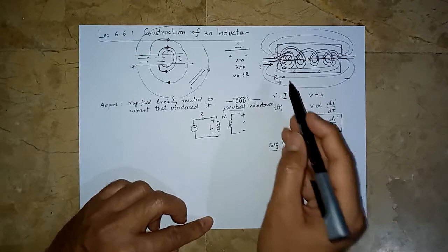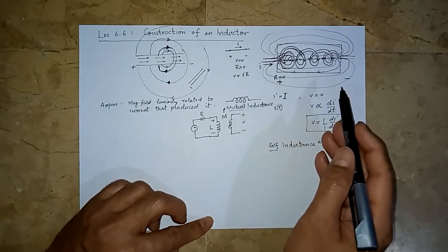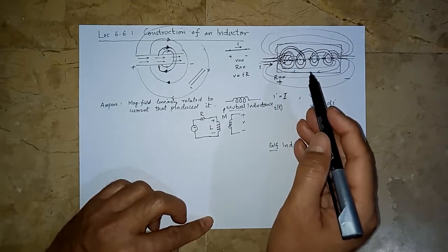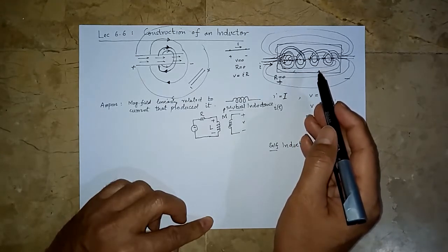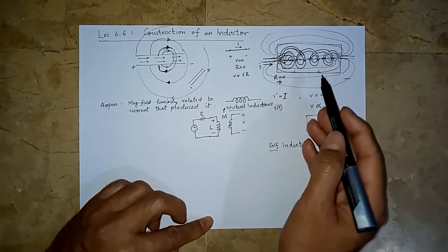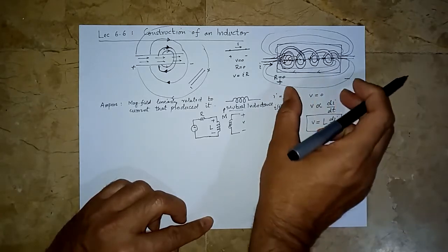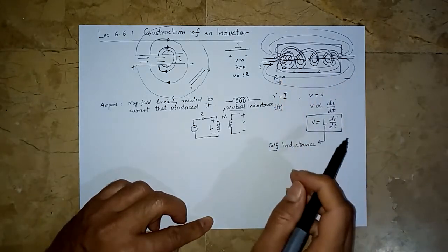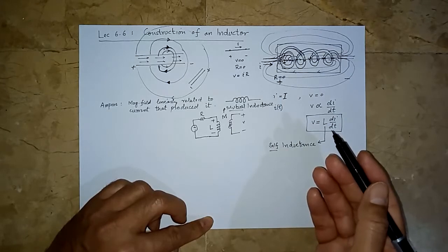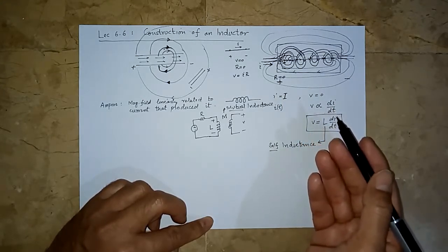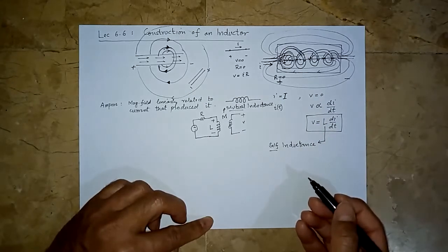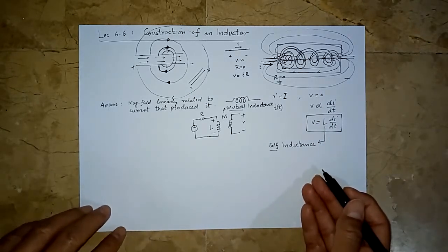This is the magic of this coil-like structure. We are going to get a magnetic field created, and that magnetic field linking with the coil itself is going to experience a voltage induced on its terminals. This phenomenon is called self inductance, and this proportionality constant is actually called self inductance as well. So this should be very simple.